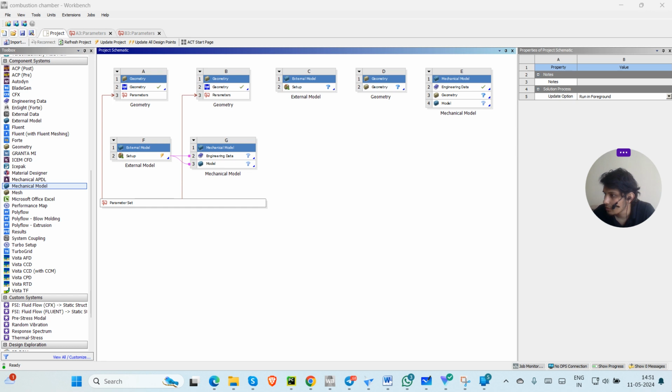Okay, so the computational domain. The NACA 0012 airfoil geometry is around 1 meter in chord length. The domain extends 20 meters ahead of the airfoil, 24 meters behind, and 30 meters above and 30 meters below. Mach 0.7, angle of attack is 1.55.